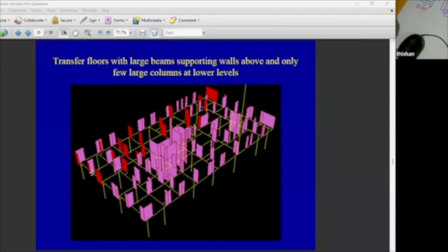So we have to artificially create that width, and when we artificially create the width, we have to be very careful with the mass and density. The moment you give the actual values of normal concrete, you will be adding extra masses and extra weight at those locations. So we have to define a special concrete for it.